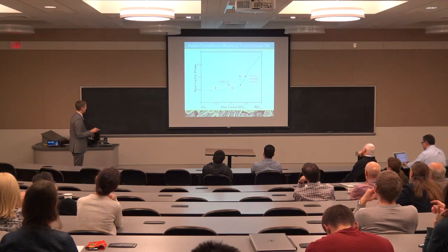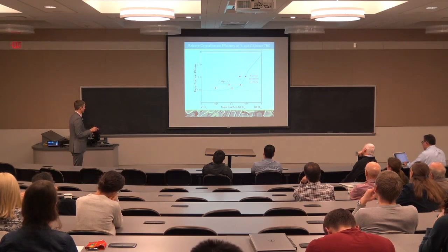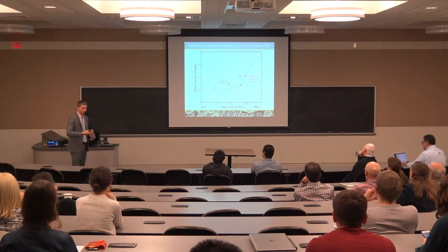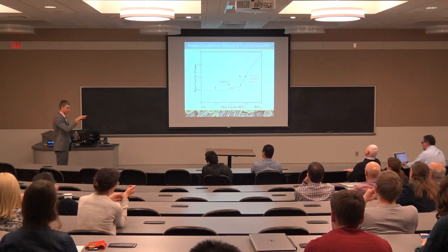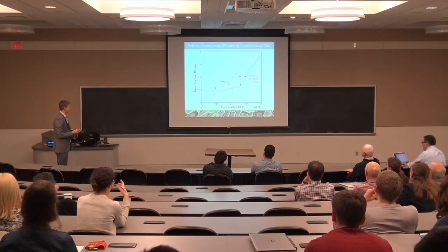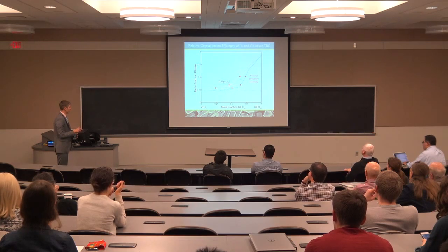And we find that we get a significant benefit from adding gadolinium. But from the flip side, if there are reasons that we can't use gadolinium because of compatibility issues with other phases or other materials in this coating stack, if we wanted to take a gadolinium-based coating that had a performance about like this and make it an yttria-based coating, we'd have to put a lot more yttria in.